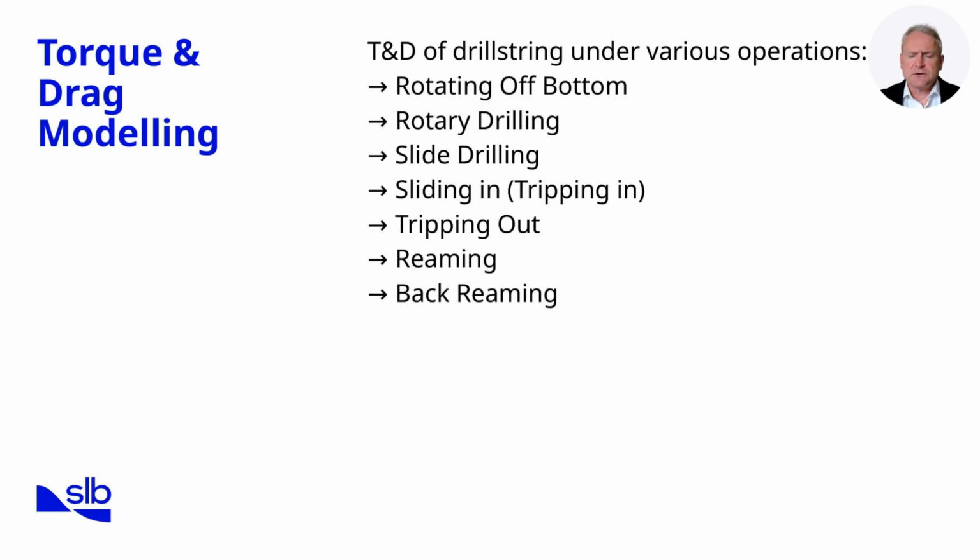Then, during rotary drilling, torque increases as weight is applied, cutting formation and creating cuttings transport challenges. In slide drilling, where we use a bent motor assembly, the drag profile changes because only axial force is applied without continuous rotation. When sliding in or tripping in, drag becomes a key factor as the string is moved into the wellbore without drilling. The opposite, tripping out, introduces overpull and potential sticking risks.